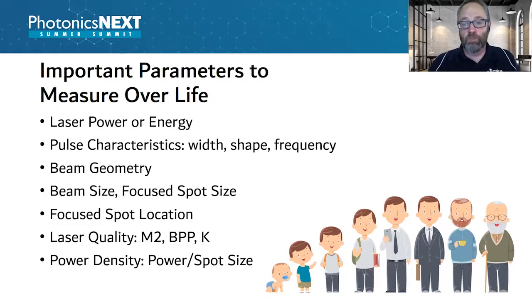So this is the amount of laser light with respect to the beam size that's being applied to the process. So if you have, for instance, a cutting application, you need to know how much laser light you have through a power meter check, as well as how tightly your focus spot is down on the material, because the laser is going to process that material at a specific power density or power density range.